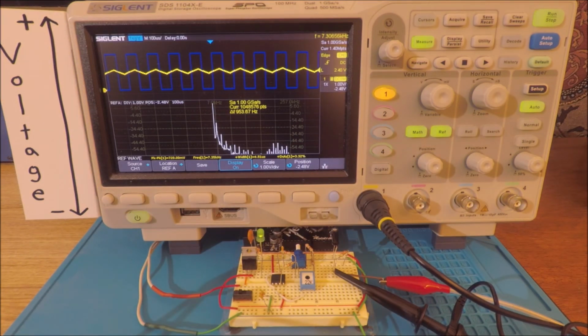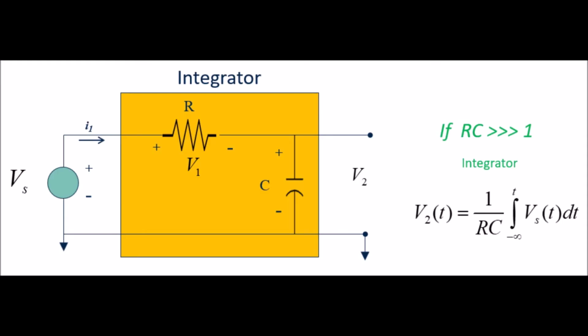The larger 1 microfarad capacitor has shifted the cutoff frequency lower in the low pass filter. This has effectively implemented a passive integrator. So we're now integrating the input of the filter, and you are seeing our square wave being filtered and processed as now a triangular wave output. There is some associated phase shift from the input to the output, and you can clearly see that there's attenuation because we've implemented a passive integrator.